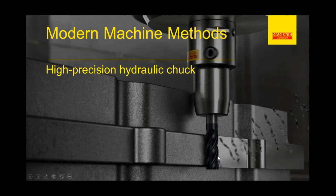We would say to our customers that we don't want the radial depth of cut with high feed side milling to exceed 20%. But we actually find that there's more of a sweet spot in that 8 to 12% area. So you'll have to do your own experimenting based on what you're cutting and how you're doing that to get the best cubic inches of metal removed in a minute.